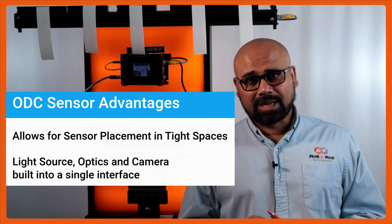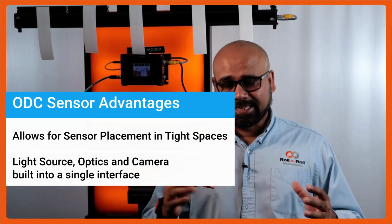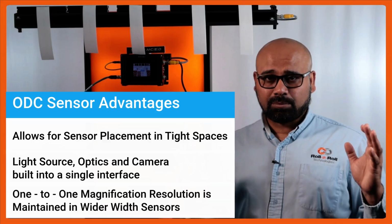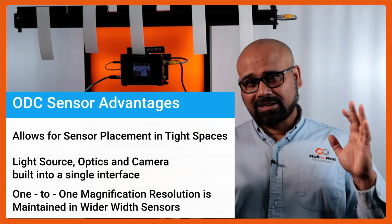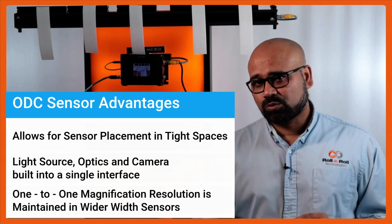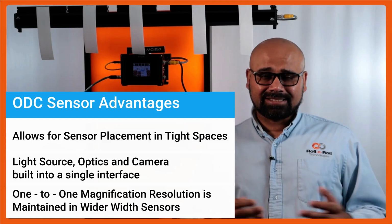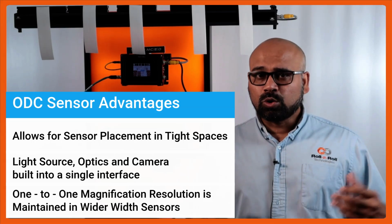We don't have to have a separate light source or gantry to have the camera and the light source built in. The third advantage is that the sensor provides a one-to-one magnification. If the object is 100 millimeters wide, we're using a sensor that is at least 100 millimeters wide. So we get a one-to-one magnification. The advantage is that when you go to a wider width, you don't lose any resolution.